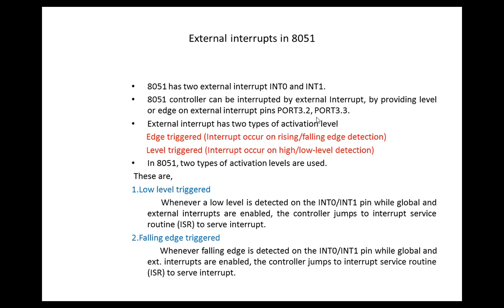Same thing here. If you want to activate your interrupt, you have to give the trigger. So in the 8051 there are two trigger levels for activation, low level trigger and falling edge trigger. Low level trigger is detected for INT0 and INT1, and falling edge trigger is also detected for INT1 and INT0, and this is for external hardware.